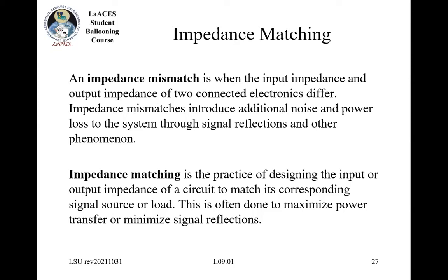For example, if I have an oscilloscope hooked up to the output of an op amp, the op amp's output impedance is very high. So in general, I want my oscilloscope to be in its 1 mega ohm mode instead of its 50 ohm mode.